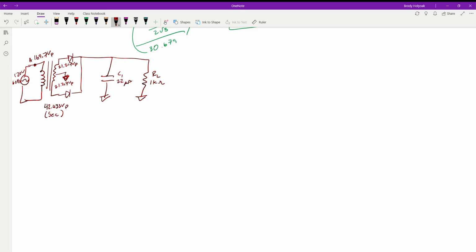And again, like before, when we take it off of the center tap, this bottom portion down here is actually going to be 180 degrees out of phase just because of the relationship between these coils. Because now we're taking it with reference to this reference point, which is no longer down here, it's in the middle. With that reference point, it flips our voltage polarity, and it's 180 degrees out of